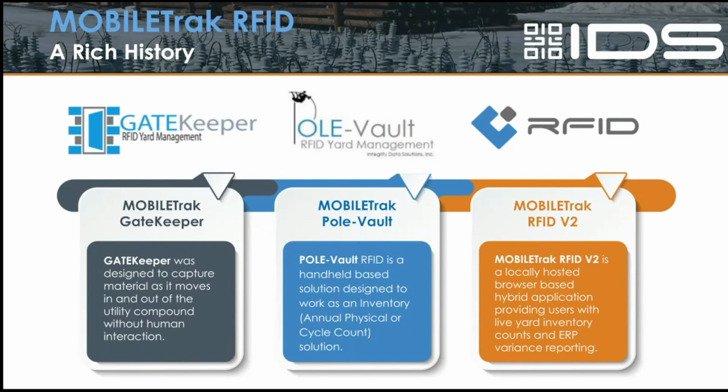So it's really designed to be, like it says, Gatekeeper. It's a fixed reader technology that is mounted at a gate that is connected to the local area network and is powered with physical power. And then we have some antennas that are mounted to a pole. And then as tags pass in and out of those gates, we're reading that tag, realizing the assignment from the tag to the asset, and then doing something with it, okay?